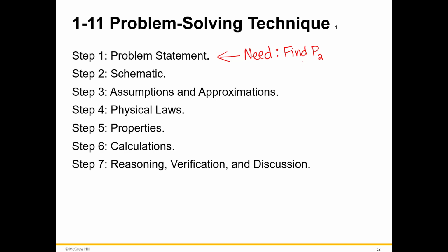And then, which for me and the students that I have taught is tried and true, draw the schematic, right? So if you're not sure what's going on, but you know it's a piston because it says it's a piston, draw your piston right here. That's not very good, but here's the system that you're working with. Here's P1, and then you've got a process. Something happens, maybe there's compression. Let's say there's compression, so this goes down. And right here, this is P2, right? So say you need to know what P2 is. That's what it wants to know.